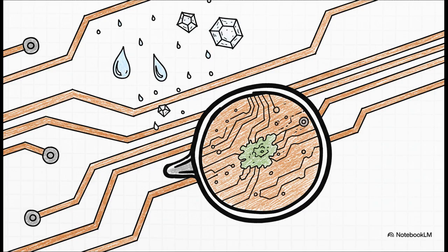And let's be clear, corrosion isn't just about giant steel structures. If you zoom all the way down to the microscopic copper traces on a circuit board, you've got the exact same enemy. It doesn't take much. Just a little bit of humidity in the air and some airborne dust can create a tiny film of electrolyte, and bam, that's all you need to kick off a corrosive reaction that can kill the device.